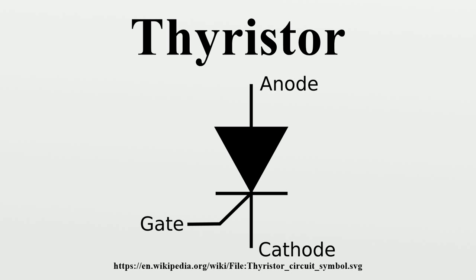The first large-scale application of thyristors, with associated triggering DIAC, in consumer products related to stabilized power supplies within color television receivers in the early 1970s. The stabilized high-voltage DC supply for the receiver was obtained by moving the switching point of the thyristor device up and down the falling slope of the positive going half of the AC supply input.